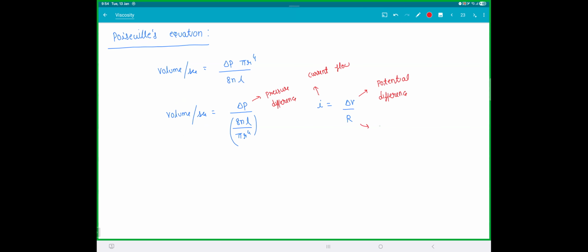This is the resistance. So this bottom is behaving like resistance to flow. Mathematically, they look identical. That means we can define something now, resistance R. This is how you actually study water flow circuits. Let's say you're supplying water to an entire building or an area. This is how you can treat them like resistors, and you can solve the whole thing.